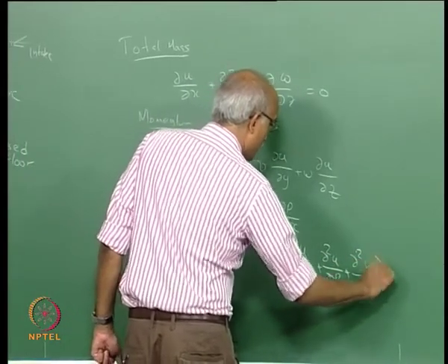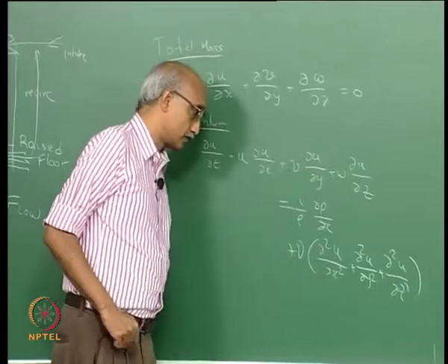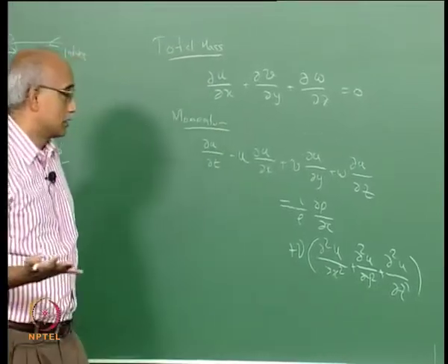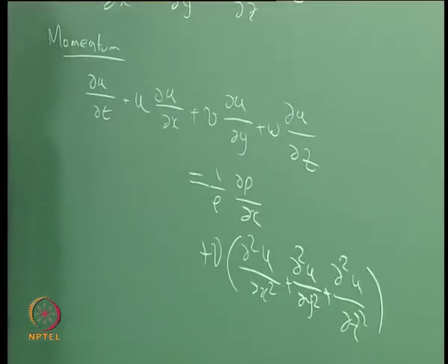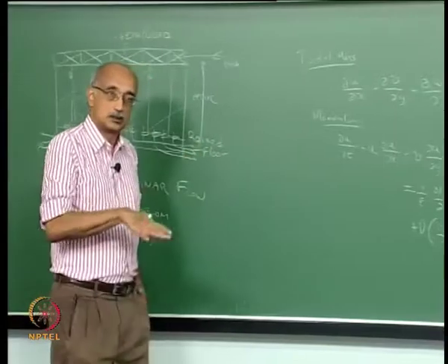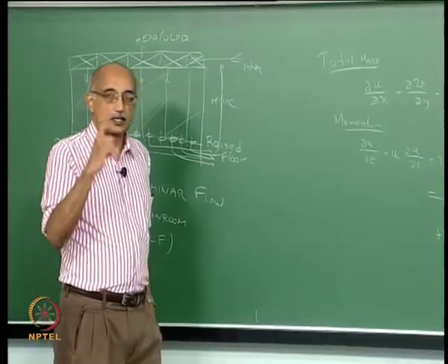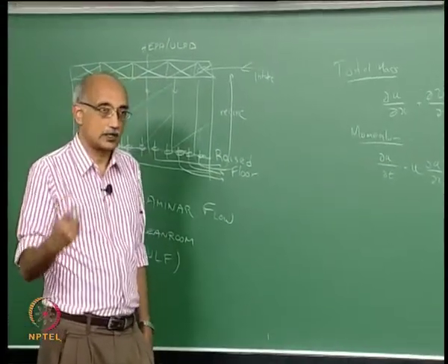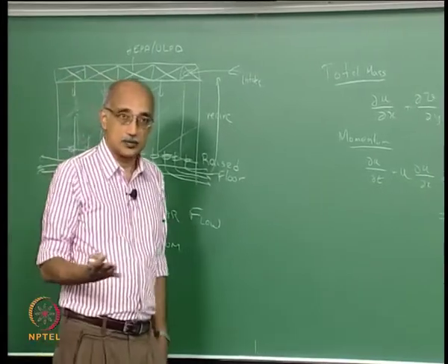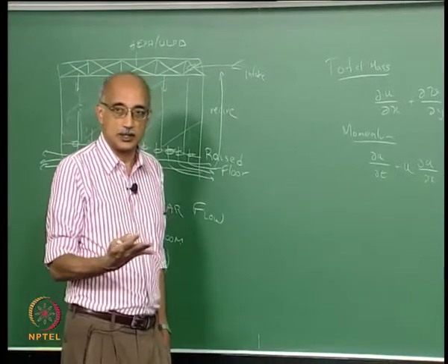So, classic momentum conservation equations, Navier-Stokes equations, can be written, and also if this is a non-isothermal clean room where there are significant temperature differences, you also have to write the accompanying energy conservation equation and then solve everything simultaneously.